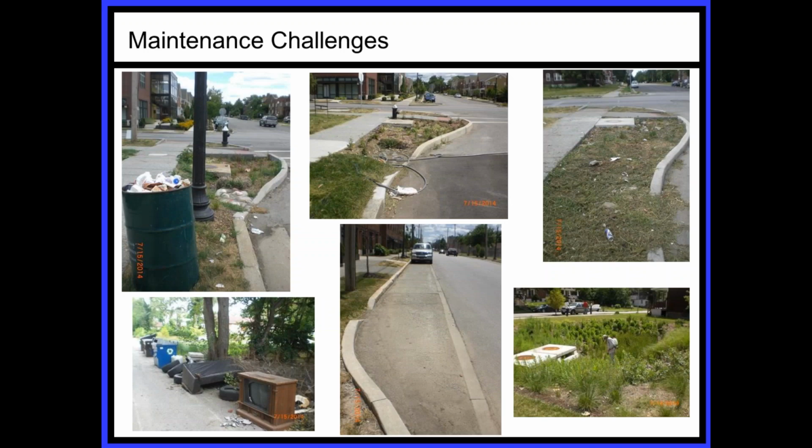Stepping back to the challenges that were mentioned by MWRD, these are in urban environments. You have challenges such as not understanding the importance of the environment around that green infrastructure, such as trash, not cleaning pervious concrete or vacuuming it. That's really what you have to do. In arid times of year, there is the importance of watering it. For example, the top center is a curb bump out with green infrastructure in an island area where they're having to pull a hose across the street to try to keep it alive.